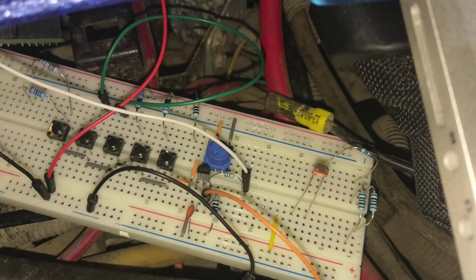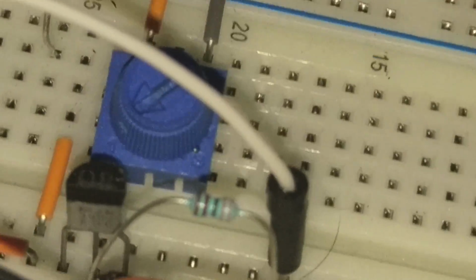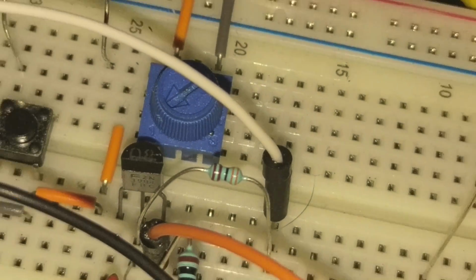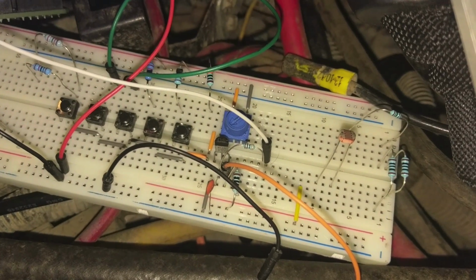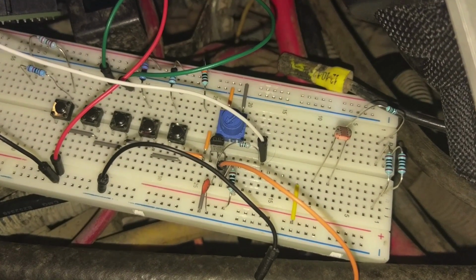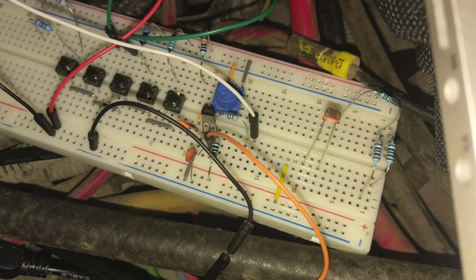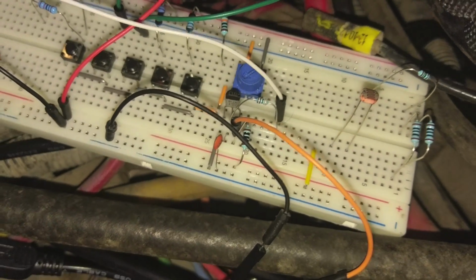But the problem is that 28K resistor, which would go right here, wasn't properly turning the transistor on and off. So I had to go back to the 3.3K resistor, and just for the heck of it, I put the capacitor back on, and all that does is go from the base to ground, and it works.